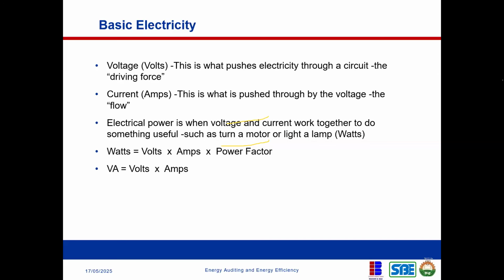Like I said, watt or kilowatt is also related with other forms of power. When you are doing some energy analysis, it's often required that you bring all your units to the same base unit. Remember when I talked about Dangote manufacturing cement, and I said the unit of their energy is maybe 20 kilowatt hour. That does not mean that it's only electricity. There are also different forms of energy, thermal, mechanical, whatever it is, but you have to convert them to a base unit, and that's your work as an energy auditor. You have to convert everything to a base unit to arrive at your final specific energy consumption, right?